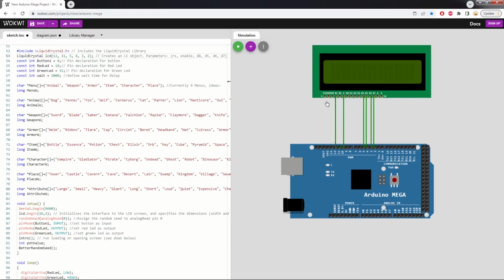And then we have to put the VSS to the ground. Let's choose the ground, and the source to the 5-volt. In my design, I didn't drive the LCD using the 5-volt. I have an LM7805 regulator to power up the LCD and play with the contrast as well.